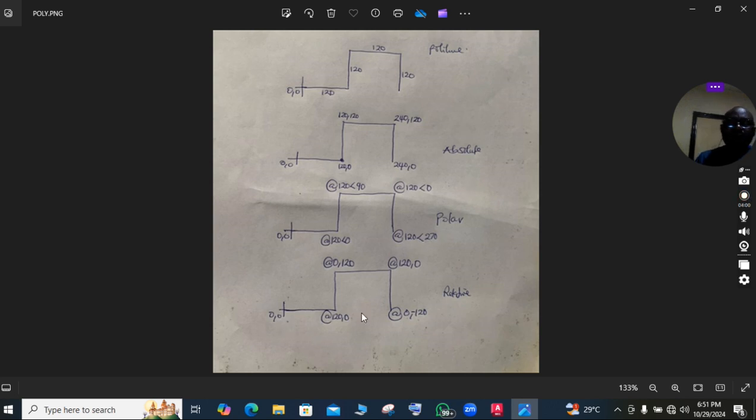That's that. And if you want to use the relative rectangular method, first point will be 0,0, and then second point will be @x,y. So x traveled, y did not travel. So @120,0. Then to get this point relative to this, it will now be @0,120. x did not move, it's only y that moved. So @x, which is 0, y, which is 120.